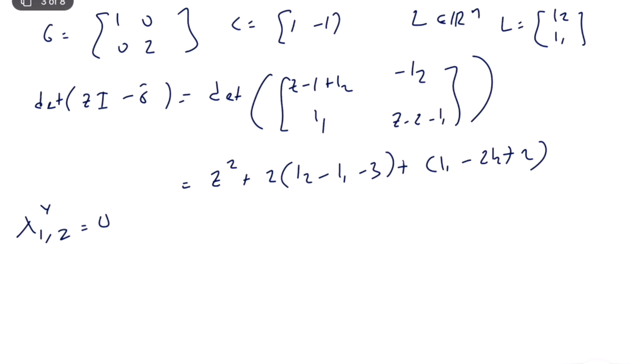So the error between x and x hat will go to 0 in only 2 steps because this is a second order system. It's a really nice thing to obtain because if I approach 0 in terms of the error between actual and estimated states as fast as possible, it means that maybe I can use this very nicely or effectively as a controller if I apply a state feedback rule. And this is the basic idea, and I will talk about this later.